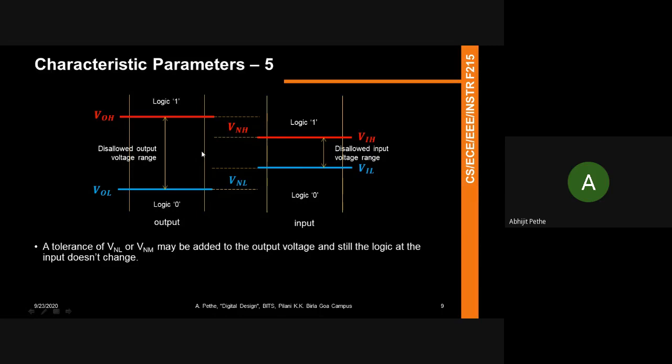When I say ICCL and ICCH, remember this has been implemented in a circuit, so certain transistors are turning on, certain transistors are turning off. The current pulled from the supply depends on whether your gate is giving an output high or an output low. So in the most generic case, the supply current is a function of what the output of your gate is going to be.